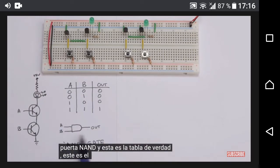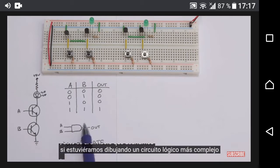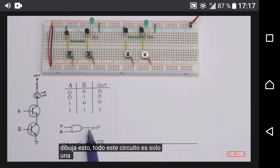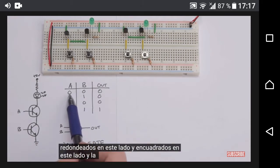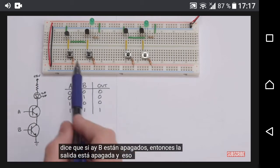This is the symbol that we would use if we were drawing a more complex logic circuit. We would actually, instead of drawing all the little transistors, just draw this whole circuit as an AND gate using this symbol. It's kind of rounded on this side and squared off on this side. And the truth table for it says that if A and B are off, then the output is off, and that's kind of what we have now.